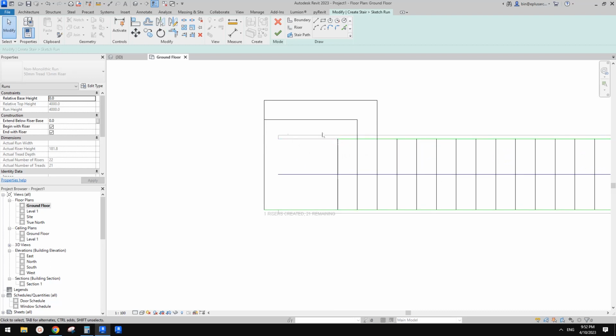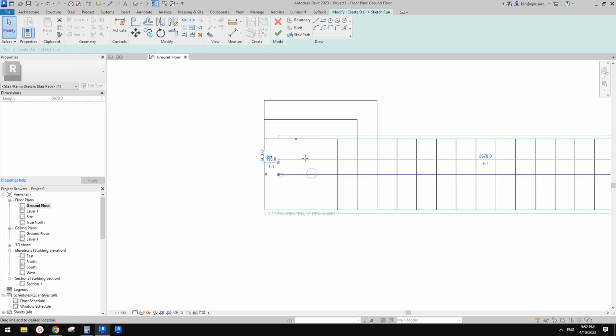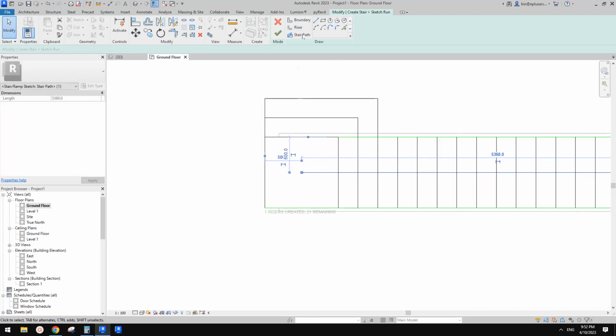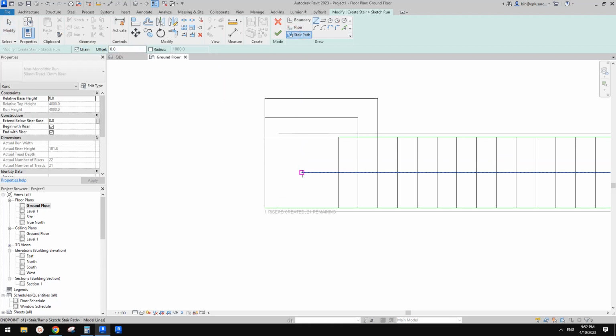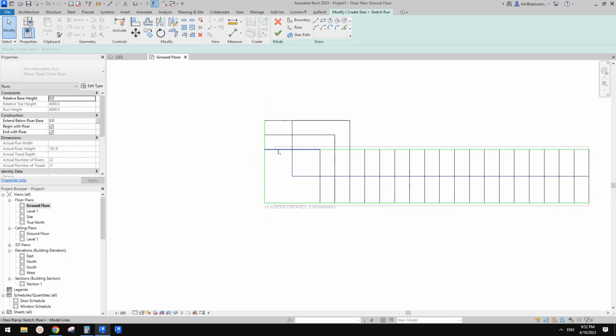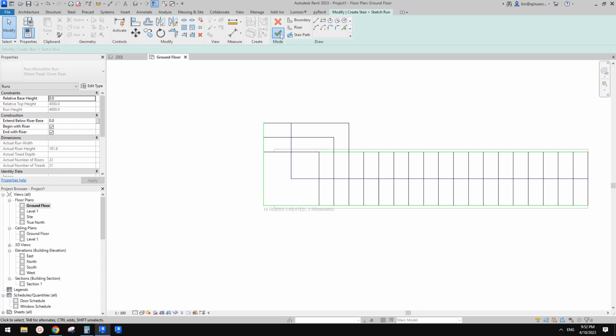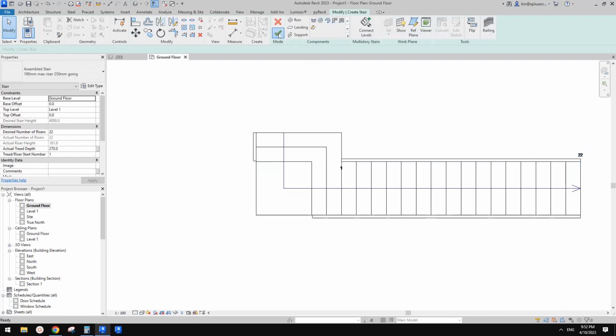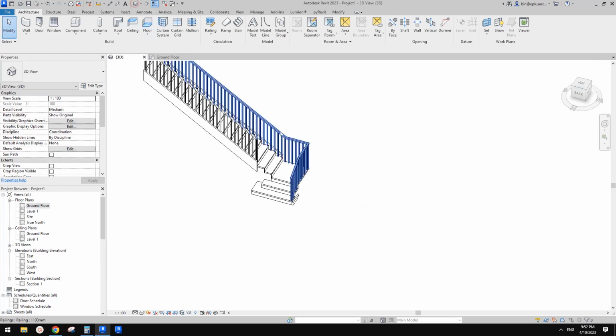So now I just need to drag this to the center point. Hang on, maybe let's trim this one first. Trim this and add a riser here, so I can just drag this to the midpoint here, and then finish this stair path. And also for this bit we need to use boundary line. So all good, trim. Yeah, so you can see boundary here, and all risers, right? So all good, looks good, finish. And then this is what we had last time, so go to 3D view.